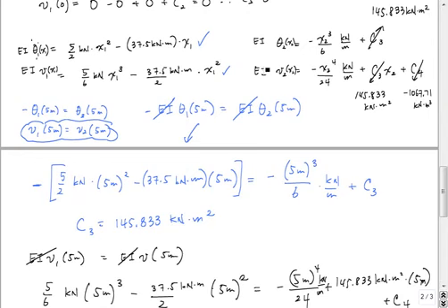The units might look a little fishy, right? But you have to remember this EI is sitting over here on the left, and it has units of kilonewton meter squared. So when I divide this through, I'm going to get units of displacement, or length. That works out fine because every term here is kilonewton meter cubed, so I'll end up with a meter. Same thing for slope, where I should have no units: every term here is kilonewton meter squared, and EI is kilonewton meter squared. So to get the actual values at any specific point at x2, I just have to make sure I divide by EI.